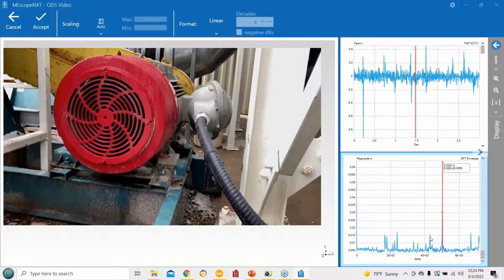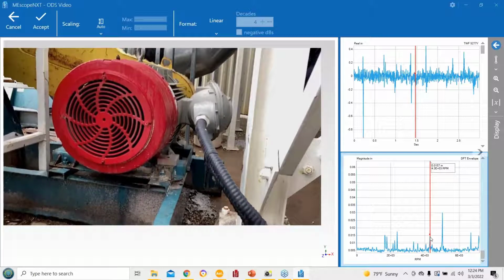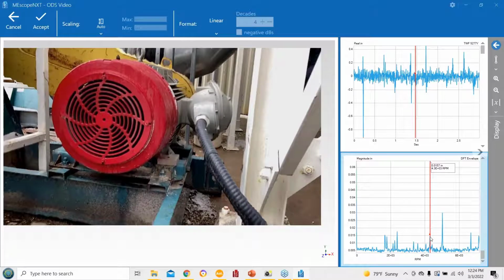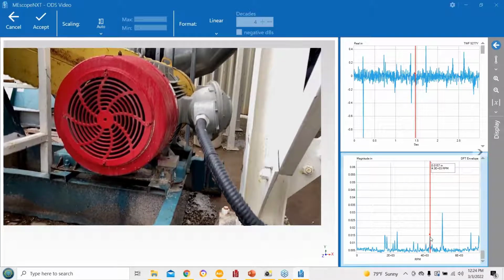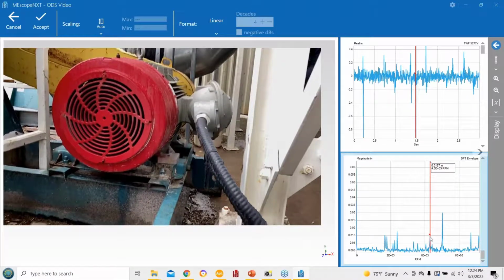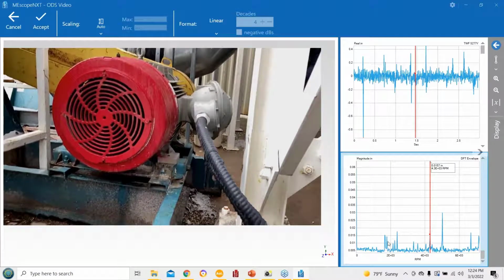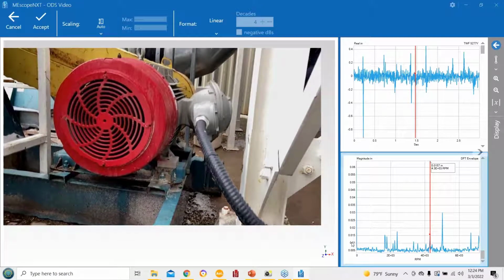And let's see what this is. Something similar. You know, there's all kinds of rigid body modes and flexural modes, and we'll pick those out. And any of them close to running speeds, that's where we have difficulty a lot of times in vibration analysis.